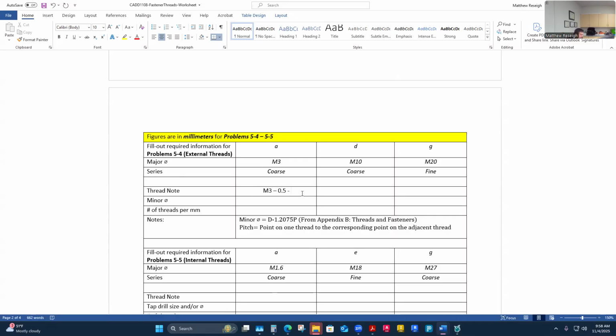In the metric system, they have a much more refined system, 3 through 9 they could designate as the class of fit, whether it's a coarse or a fine kind of fit. Not necessarily a coarse or fine thread, but just the fitting relationship, how tight or loose the tolerances are on those parts fitting together. Grades 3 through 5 are fine, and 7 through 9 are coarse.